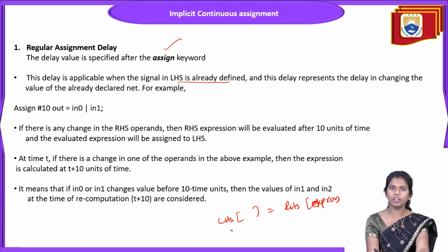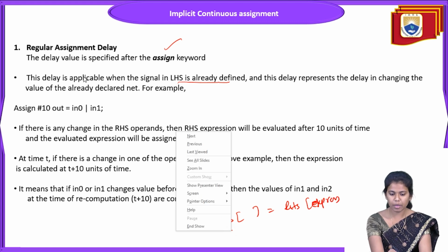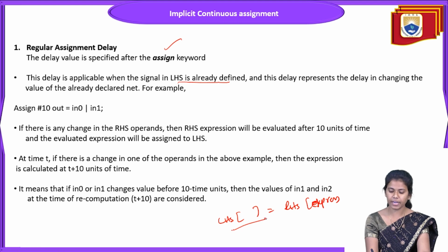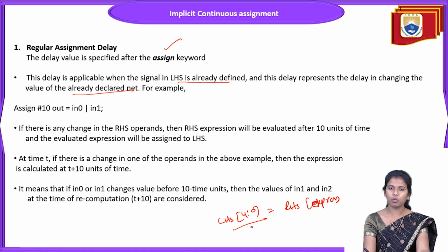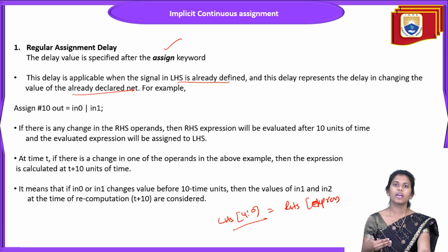It represents the delay in changing the value of an already declared net. That means when the delay is declared on the left-hand side of the continuous assignment statement, the net is also already declared somewhere in the expression.